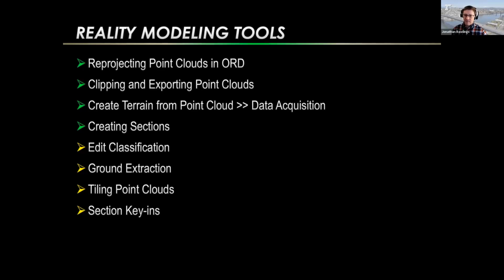I've said it's been kind of convoluted in the past as far as doing that in MicroStation. And Rhonda did a webinar on Blue Marble and reprojecting in Blue Marble, which is still the preferred method, especially if you have more than 3 or 4 point clouds. But there is a method in MicroStation that you can do. So if you only have 3 or 4 point clouds, maybe 5 point clouds you want to do quickly, you can quickly do it in MicroStation. So I'm going to go over that today. And then we're also going to touch on clipping and exporting point clouds in that process.